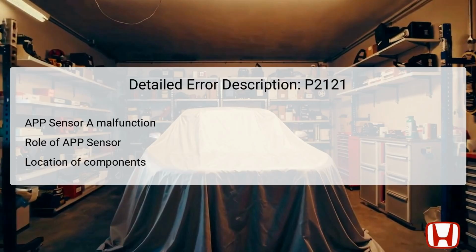DTC P2121 signifies an issue with the APP sensor A, responsible for relaying the position of the accelerator pedal to the PCM. This sensor is essential for ensuring that the engine responds correctly based on accelerator input. It helps manage the throttle angle and affects acceleration, fuel efficiency, and emissions.